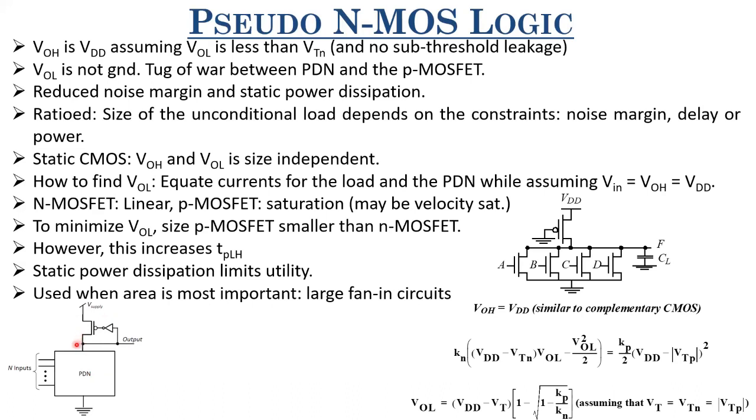But in that case, once it is discharged to the ground, can we charge it to VDD again? No, that's an issue. So this design was discarded. Although it was able to realize this full logic swing, the moment this node discharges to ground, can we charge it again using the same circuit? No, we'll have to use another circuit to charge it. So that reduces its utility, or I would say that was a disadvantage. But the advantage in terms of area, let me show you that.